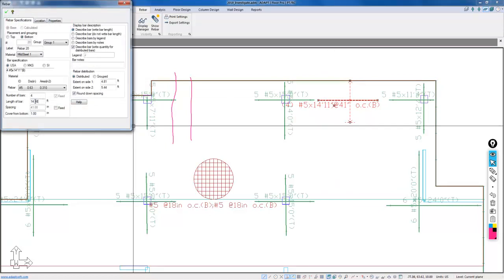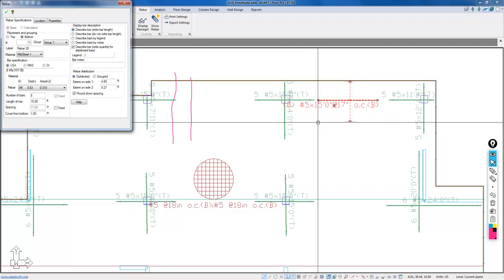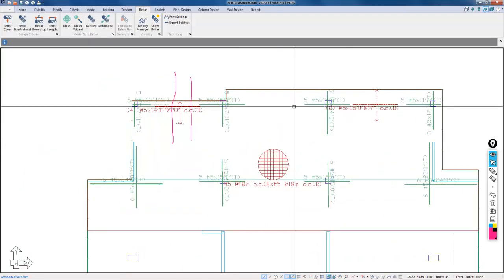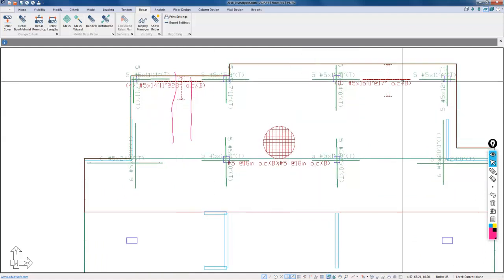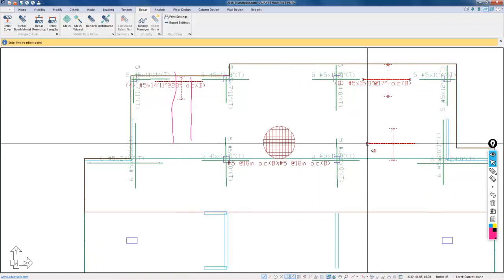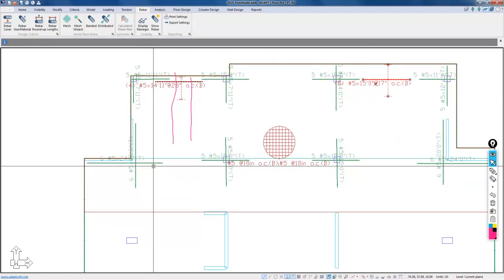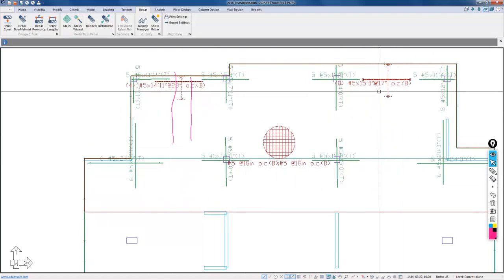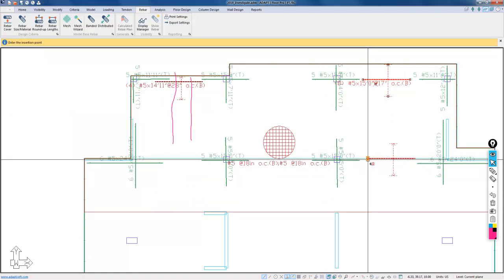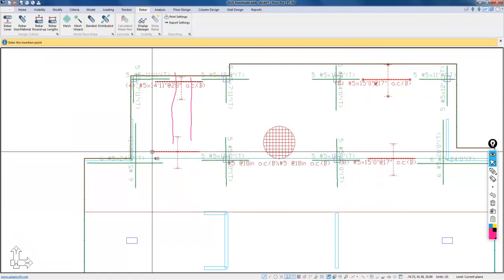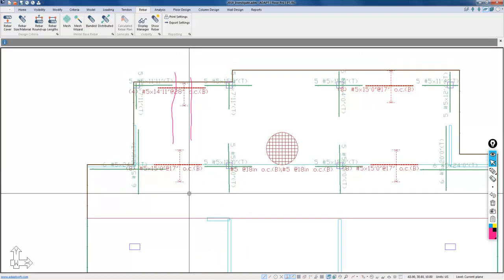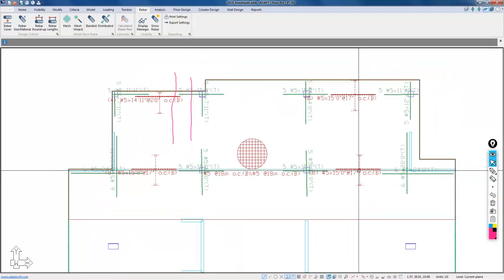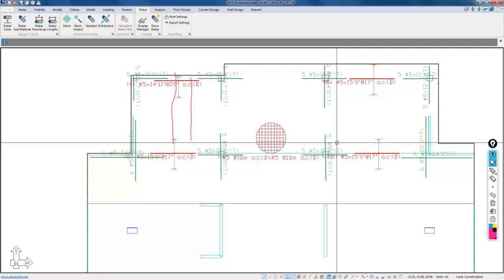Okay, we're now going to go ahead and extend the range here, and I'm actually going to say that this is a 15-foot bar, and we're going to use 8 bars here in this bay. Okay, we're going to have no additional bar in this midspan here, and then we'll go ahead and copy this down again. We'll just reuse that. Make sure we snap to the right spot there. So there's 1, and I'll reuse that there also, 2. And I'll just leave those as is. You've seen how we can edit those and manipulate them.